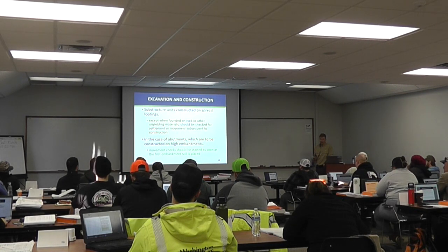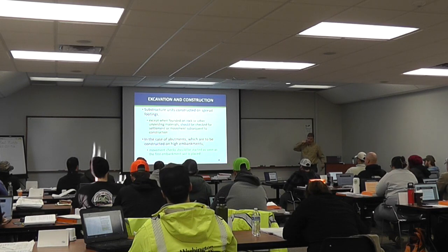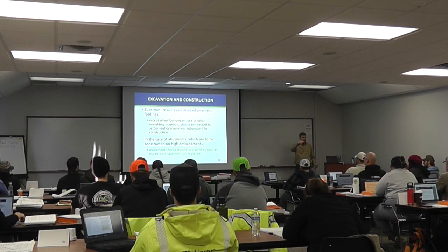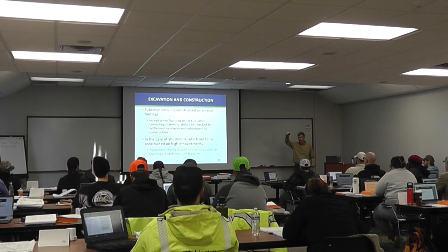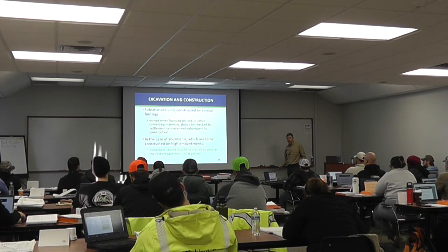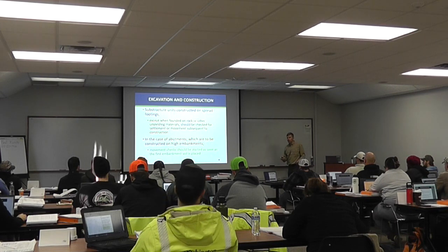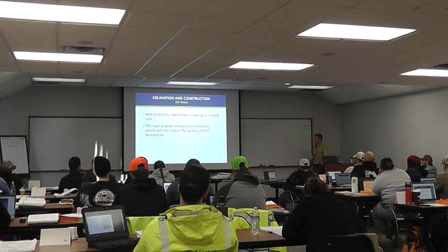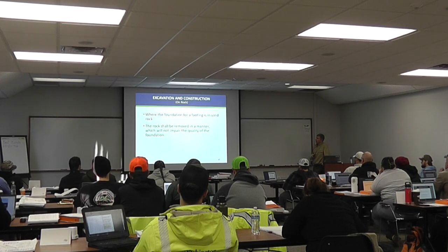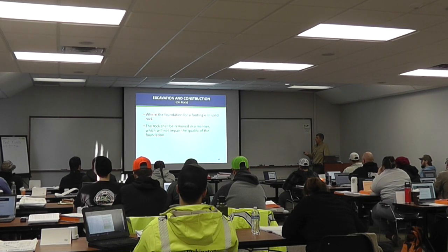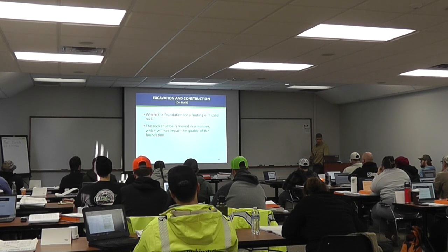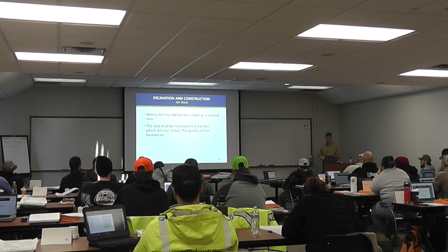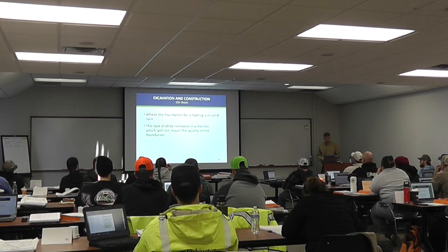So we should check for settlement, is what this slide is saying. Oftentimes that's as easy as you just mark it with a magic marker on your footing or up on your stem or something, and then track it over time. And it's good information to know if we are doing any settlement or what's going on. And then movement checks should be started as soon as our first stone is placed. If we're in solid rock, rock has to be removed in a manner that doesn't impair the quality of the foundation. So obviously we don't want to damage the rock that our foundation is on.